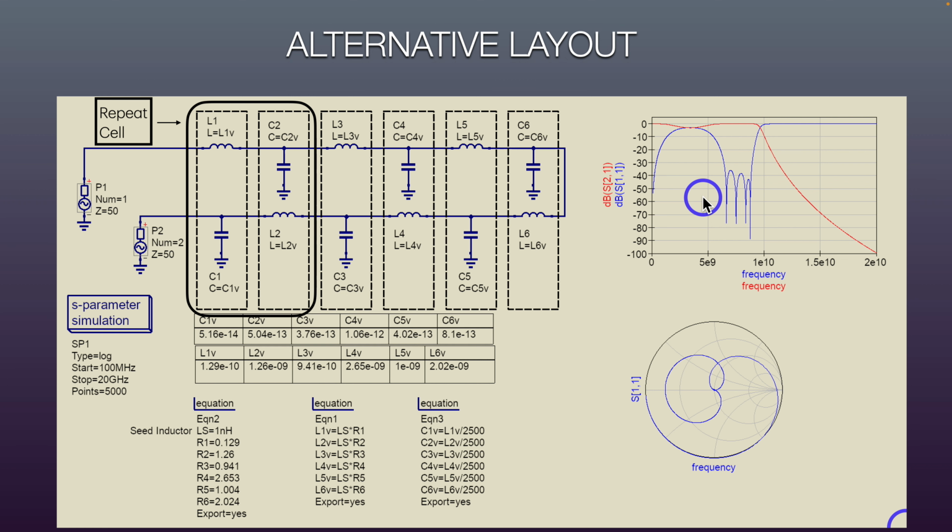So what that lets you do then is just squeeze all those resonances together, and in a lot of cases, rather than having a low pass filter with a lot of ripple up here near some particular frequency you're working at, you may want to have better performance right around that frequency, and then still an improved cutoff frequency performance.